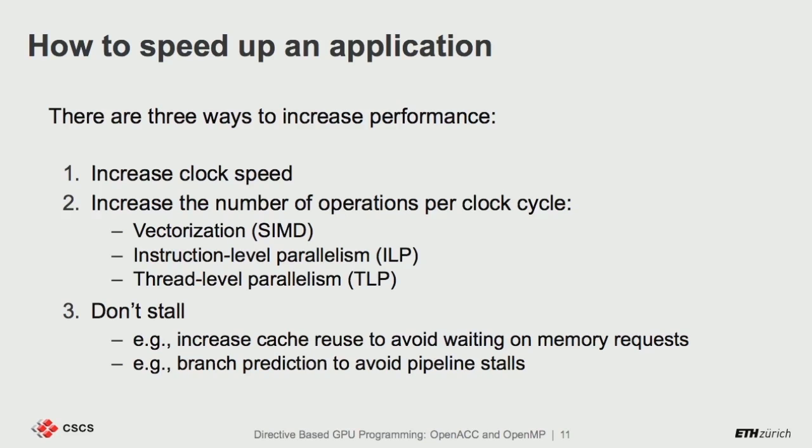So with a single instruction, you do 4 real additions, 4 real floating point multiplications. So this basically increases parallelism without increasing the frequency. What that means is we don't increase the power envelope of our processor, but we actually increase its performance.